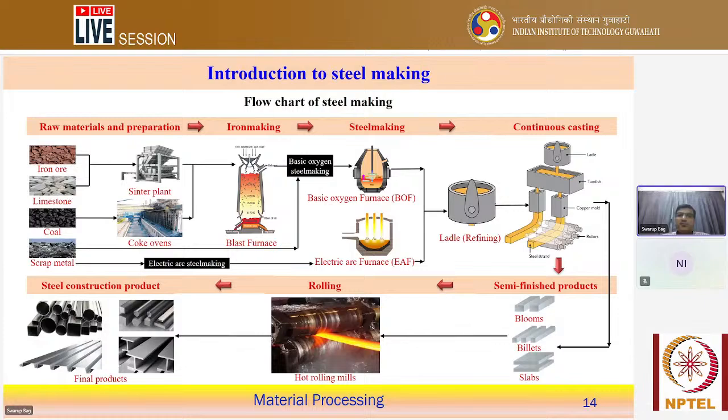But single crystal materials are not something we can make in the ordinary steel making process; here the process is different, because the solidification is usually controlled in the single crystal production system, such that a uniform and continuous crystal structure is maintained throughout the entire material. The heat extraction from the metal is controlled and directed in one direction, such that only a single grain is produced, to avoid the formation of multiple grains or a polycrystalline structure.